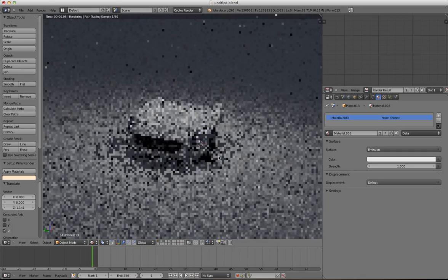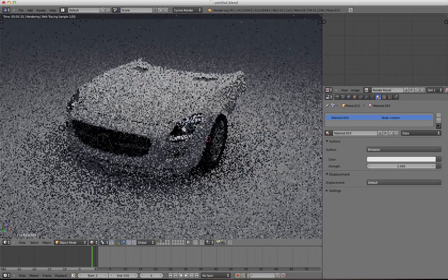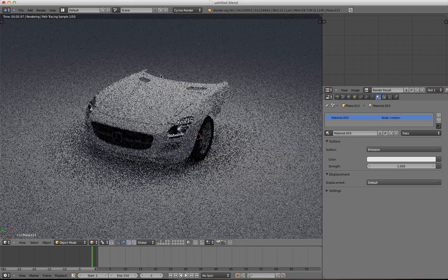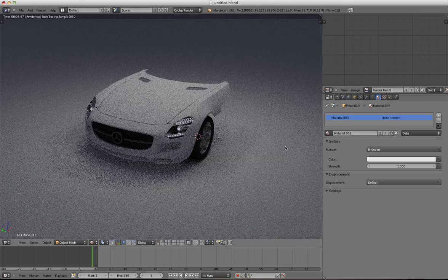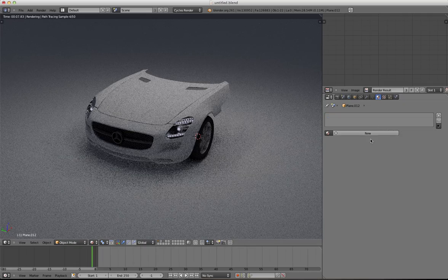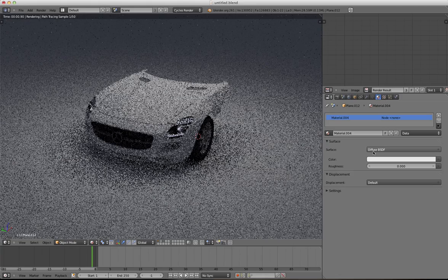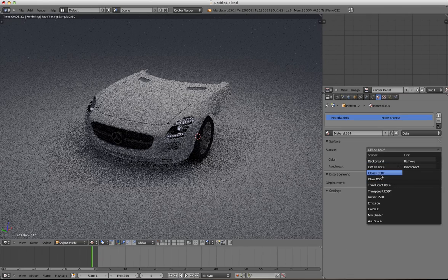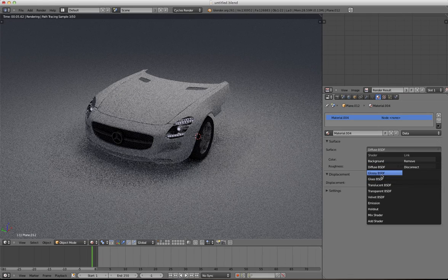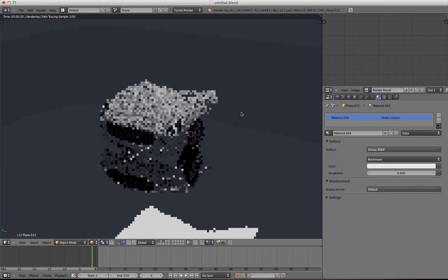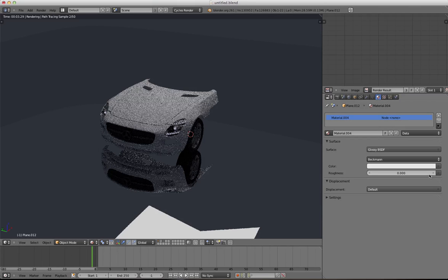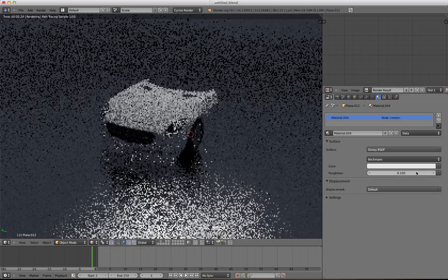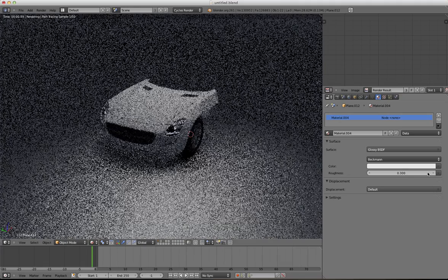As you can see, we have already a nice lighting setup here, and we can move on to setting up the materials for the background of the car itself. Now select the background and add a new material, and for this object select a glossy surface, yeah, like this, but we don't want it to be that blank, so add a roughness of 0.3, I think that's fine.